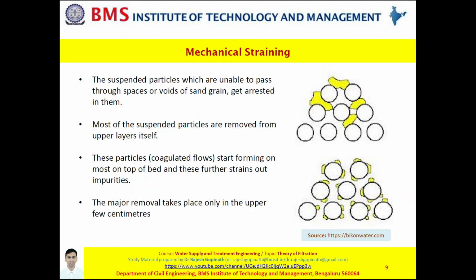The advantage is that most of the suspended particles are removed in the upper layer itself. However, we also need to understand that it is only the first few centimeters wherein the major removal takes place. Nevertheless, the entire depth of your filter bed is of importance. How, we shall see further on. Slide 10.